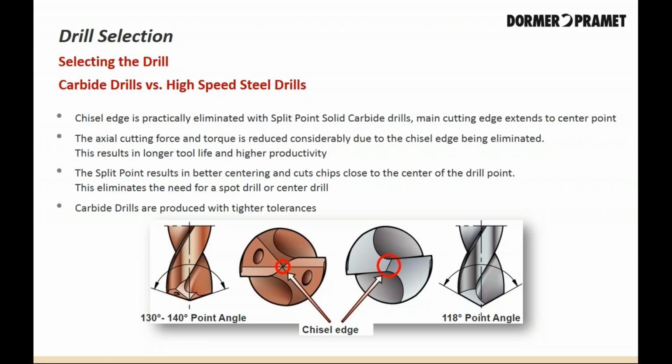Hardened material. Solid carbide drills are hard and can thus be used for machining of hardened material up to about 60 Rockwell. Because most HSS drills are only marginally harder than that 60 Rockwell material we're machining, they are not really suited for these kinds of applications.